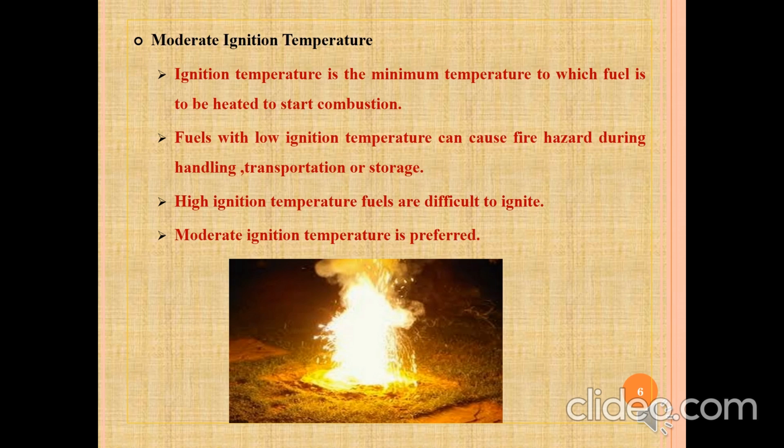Fuels having a low ignition temperature can cause fire hazards during handling, transportation or storage. So it's very risky to handle a fuel which has a low ignition temperature. But if the fuel has a high ignition temperature, it requires a lot of energy to ignite the fuel to start combustion. So a moderate ignition temperature is the best way to start combustion of the fuel.